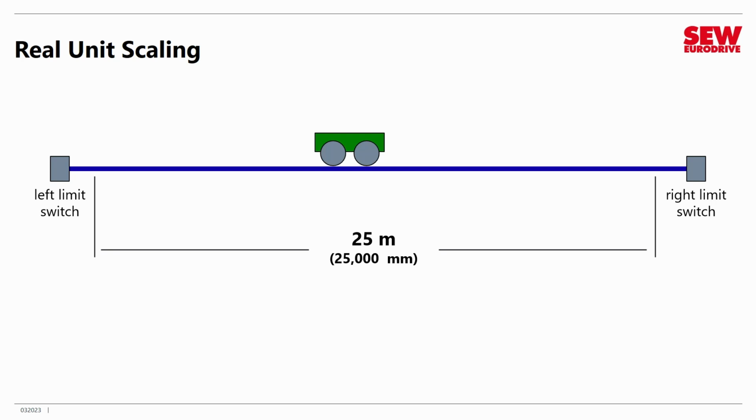How do we set this thing up? Well, if you think back to our math session, which was a very long time ago, you remember that we wrote a program that related real units to increments for a roller-type conveyor belt. Well, this is basically the same kind of scenario. In fact, we're going to reuse some of that code for one of our example programs before we're done with this session. Now, when we're dealing with a situation like this, we need to know the application parameters. We need to know things like roller diameters, and we need to know gearbox ratios and various other things. Let's step through the math here and kind of work this out.